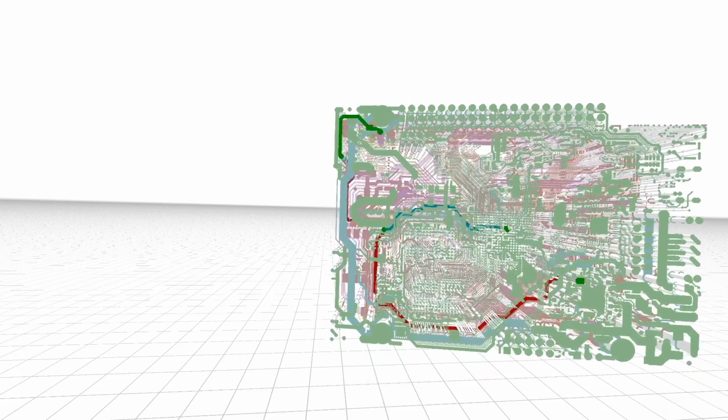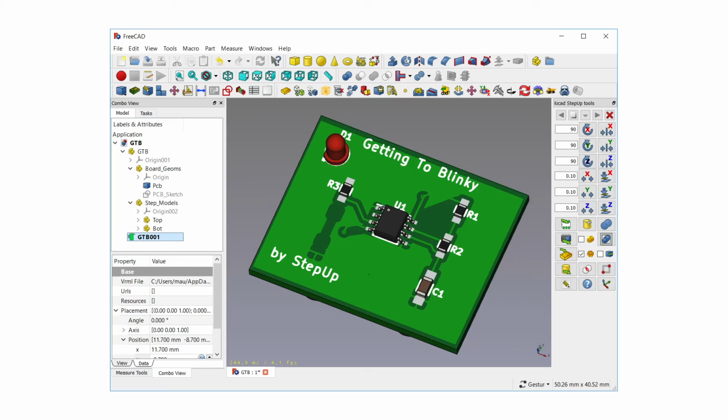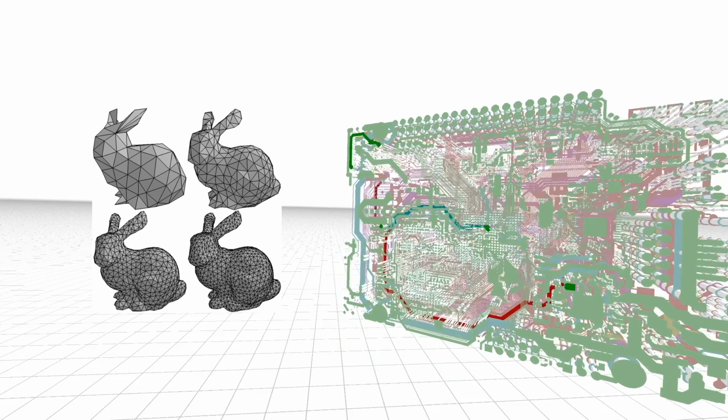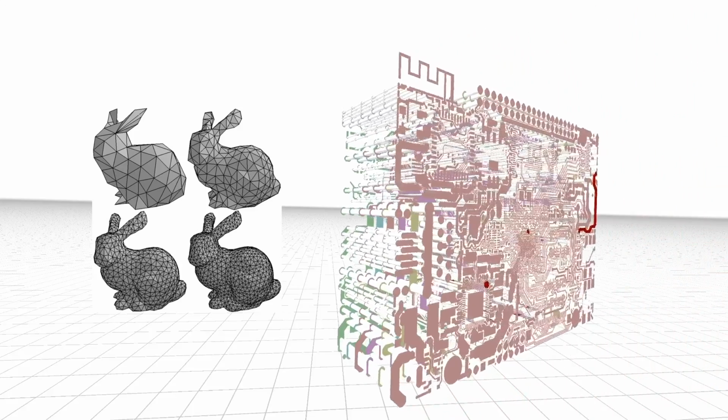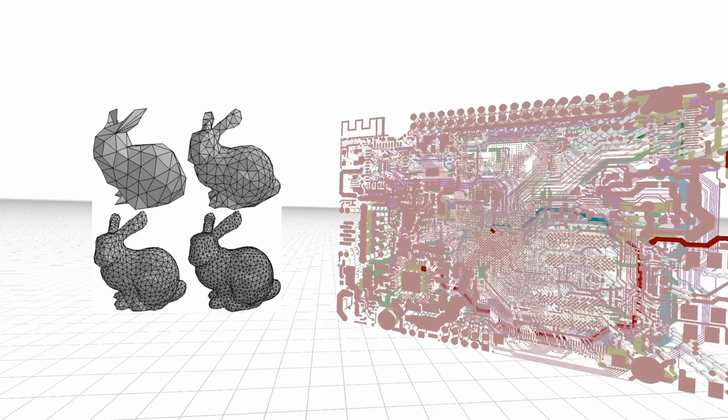KiCad has an existing 3D renderer, but it only renders a static image on a 2D window. In that rendering mode, KiCad iterates over high-level board features like traces, vias, and component footprints, collecting them into lists of triangles in memory. Along with a few architectural changes, we were able to use the same rendering logic as a model for the implementation of our own GLTF exporter. Let's have Ashwin talk about how we actually launched the Godot VR view from KiCad.